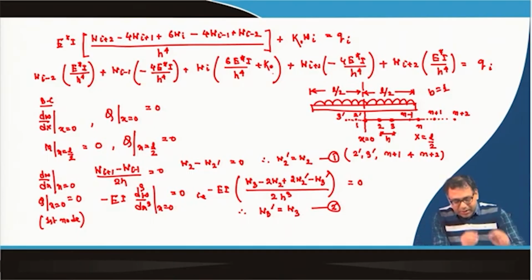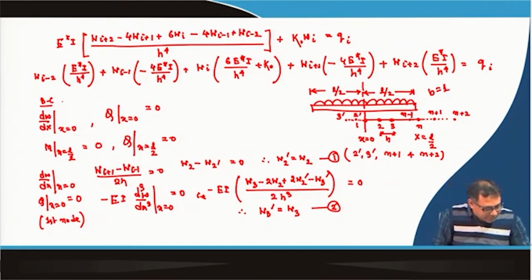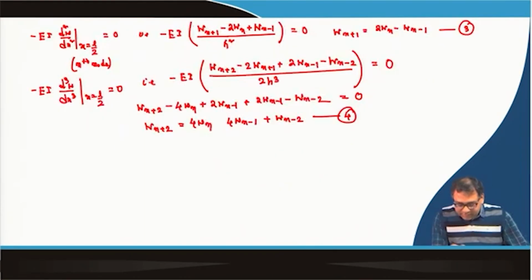So, now you apply these basic equations in finite difference form in all the nodes from first node to nth node, and if in some nodes, basically these 4 nodes, when you apply these equations, the imaginary node will come. So, those imaginary nodes you replace with real nodes. So, finally, you have the n number of equations.